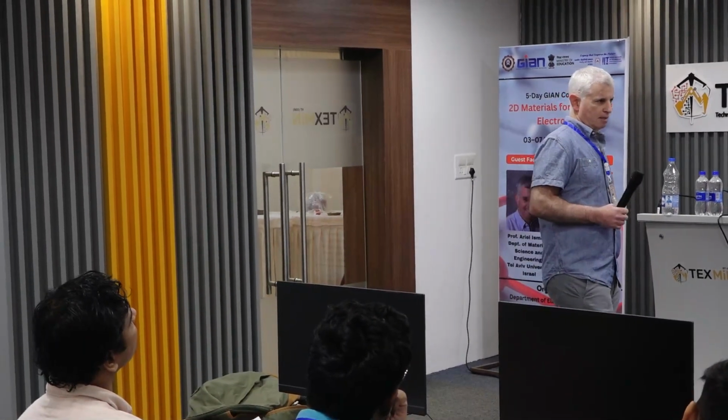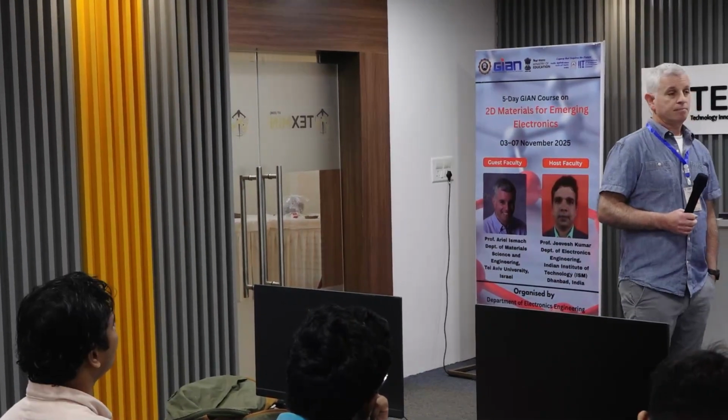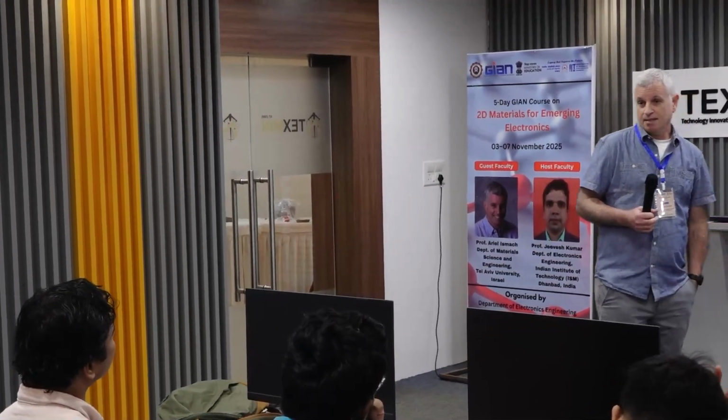So the preferable crystal structure. We'll talk a few words about epitaxial growth. You can grow epitaxial graphene on 111 copper very well. Epitaxial graphene meaning that it's mostly single crystal. So the 111 plane is preferable. For CVD also, well, if it grows epitaxially, it's the best result that we can get. Single crystal all over.